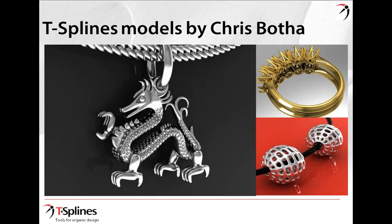The little thing underneath that was a command I found in Rhino: extract wireframe, extract. That sounds right. Yep, something like that. And I made a sphere and extracted a wireframe, and I just ran the TS pipe command. So everything you're looking at on the screen so far has all been TS pipe. Yeah. TS pipe has been a really, really big friend to me.